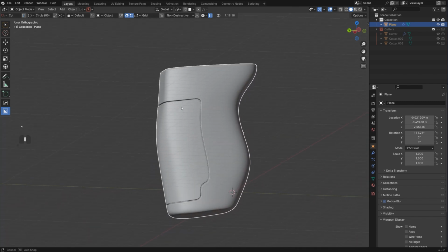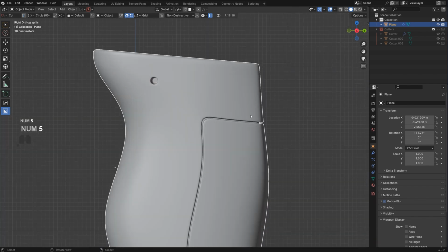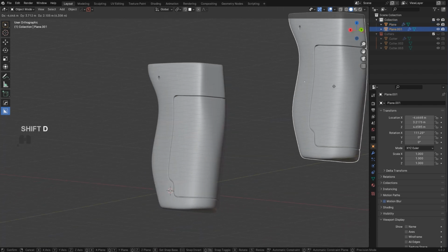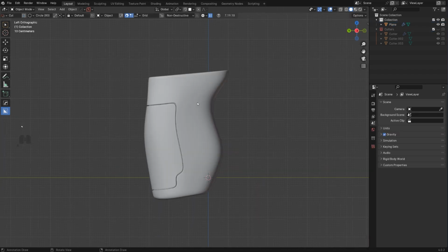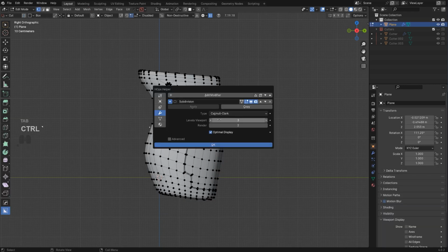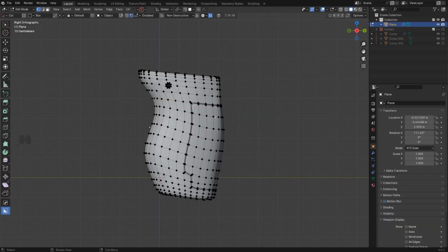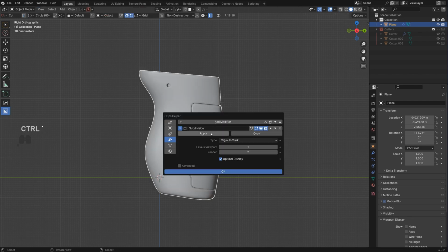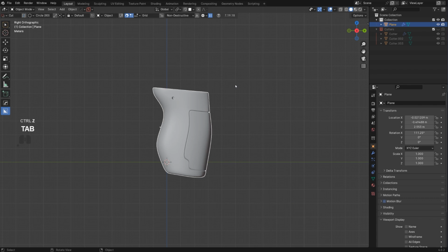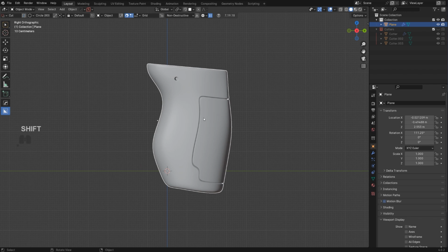And what you want to do is just basically try something and see if it's gonna work. You can create a duplicate of your mesh and create a backup, so you can always come back, because when you apply subdivision, this is destructive, right? If I'm gonna apply one more level of subdivision here, it's gonna be much denser, right? And I cannot go back. So this is gonna be very difficult to revert the changes. Anyway, so these would be approaches to sub D you could take, depending on what you're creating and what you want to achieve.